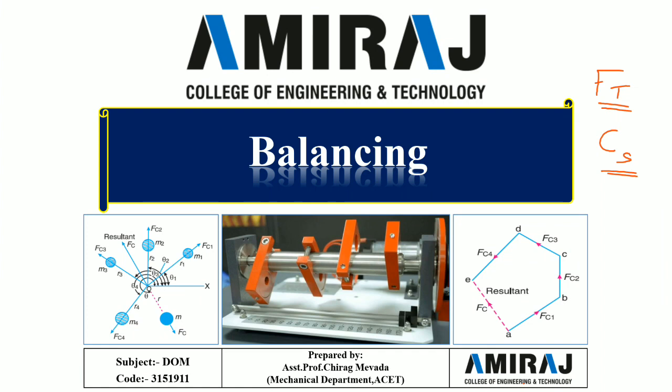So basically the tractive force was the resultant unbalanced force due to two cylinders along the line of stroke, while the swaying couple is the couple formed when the two cylinders are along the horizontal direction, due to that unbalanced force, that is due to the tractive force. And the third one was hammer blow, and that acts perpendicular to the rail.